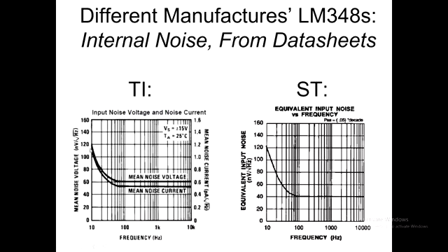And let me say, it's a lot easier if you have the units in volts squared per hertz to make that projection, even though it's an oddball. Yeah. If you get it in mean square rather than RMS values, it's easier to make that projection from a graph, like here, to the white noise level. The white noise level we can pull out here quite happily, can't we?